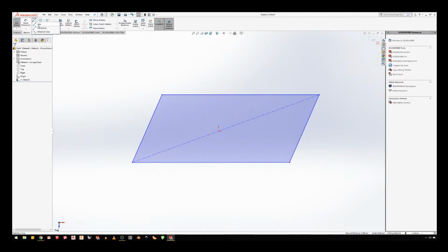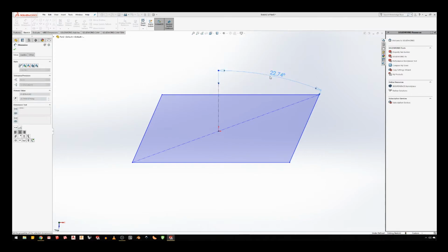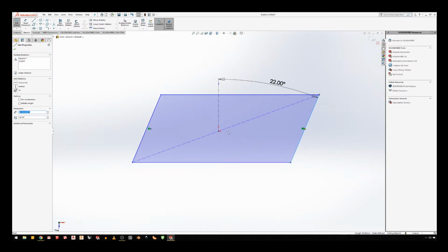And we could throw in another center line and go vertically, and then use that to give ourselves an angular dimension for this parallelogram. Let's say 22 exactly. And there we go. These lines are parallel, as suggested in the name parallelogram, but we can see these little green relation squares indicating thusly. And we also have that relationship on the horizontal as well.